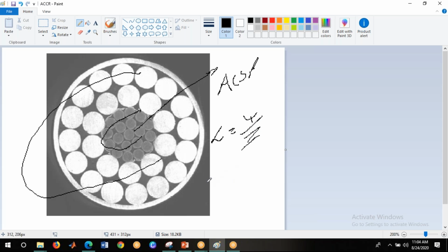We already saw the inductance in one video. The purpose of an inductor is that it limits the flow of current, and the inductance depends on the amount of current at which the flux linkages happen in the conductor. That is given by L. Now here we are going to derive this equation: L is equal to psi divided by I.